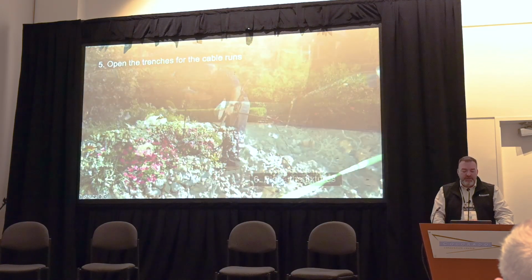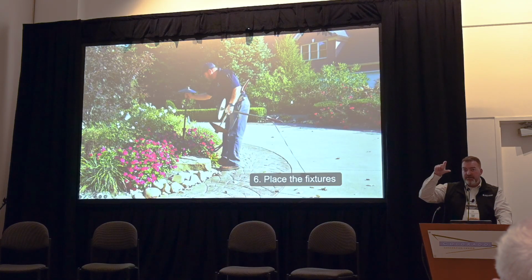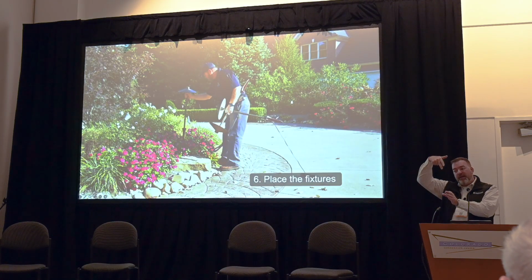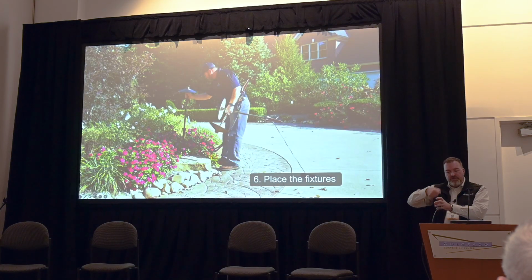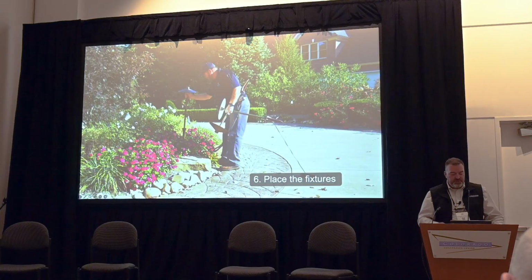It's not bad. We recommend, if you can, minimum cover. The NEC, it used to be minimum 6 inches of cover. Now with low voltage circuits, now they've gotten crazy where you can actually lay them on the ground and they don't care. But that is a terrible way to do it because you don't want to see cables laying around. So minimum 6 inches of cover, and stake them down with sawed turf staples in places, because what will happen is that iron, it'll start to build up, it'll rust, and it'll lock into the ground. You can't pull those staples up. And so especially in Michigan and areas where you have freeze-thaw cycles, as you're going out and doing service contracts, you'll see that cable start to push up out of the ground if it's buried too shallow or it's not stapled down. So just take extra precautions, staple those things in as you're going along.